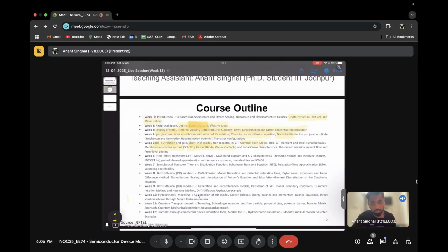Those are some important topics, because as you might have seen in the previous lecture, the contacts that we were making around the MOSFET, let's say we try to make a contact from the source. Source is always very highly doped, because we do not want a very high difference in the doping around the contact. If we dope the source highly, it is almost equal to that of metal. So the contact that we apply is always of metal. If we don't have much doping difference, then it will act like an ohmic contact. That is what we want. We do not want any barriers to come in between whenever we are giving some voltages. So you need to be aware of the concept.